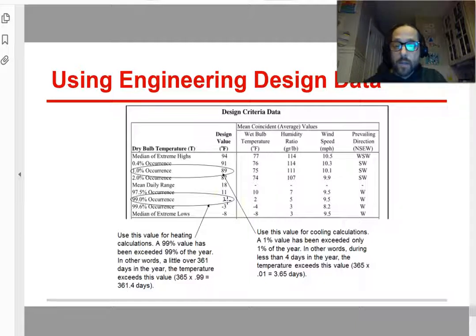If you think about designing your HVAC system, you have a house and you're trying to figure out how much heat you need. How big is my system? Do I need 100,000 BTU? Do I need 80,000 BTUs per hour? In order to do that, you need to know your design temperature. If it's 89 degrees outside, and you usually use a base temperature of 65, you say this is just about the hottest part of the year, and I need to cool it down to about 65.